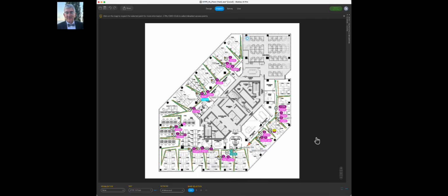Now we are in the last stage of this process. Once we have done the optimization process, what we need to do is load the project file either onto a mobile or PC, conduct a secondary survey near or exactly on the same path that we have done the primary survey. And if you notice, the primary survey is marked in green, the secondary survey is marked in yellowish gold color. So what we can do now is we want to see exactly these surveys.